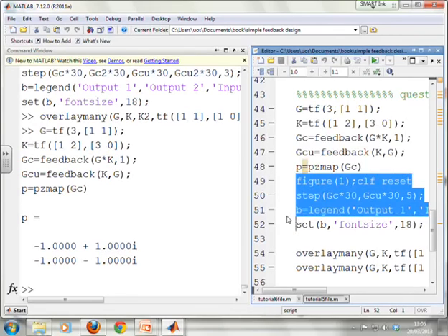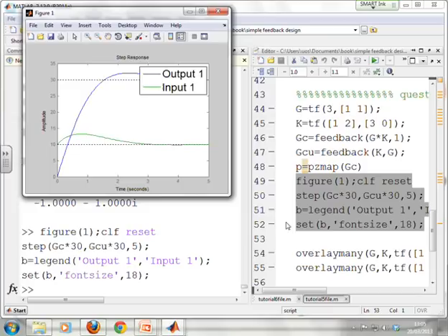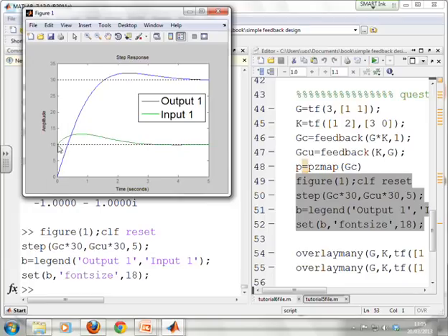I can do a figure for this and see what's happened, and there you can see the output response overshoots slightly the input response. The input starts at the right place but goes a bit too big, and that gives you an indication I'm integrating up too fast based on this error, and that's why the input has gradually gone too large and why I've ended up with this overshoot. So the plots also give you an indication of what might be wrong with this compensator.